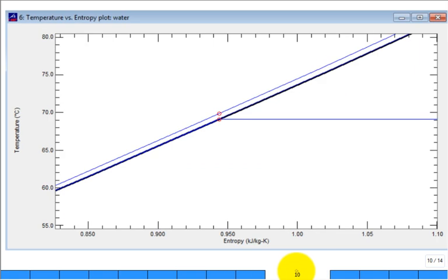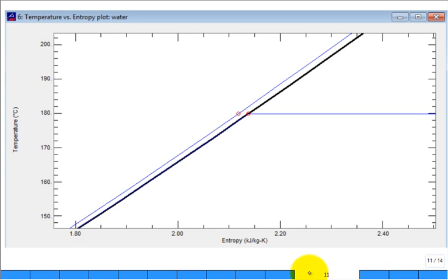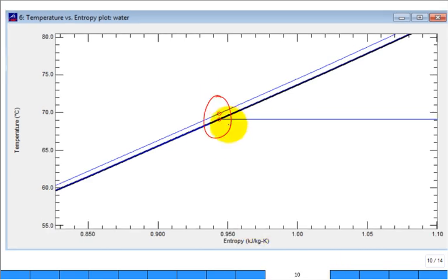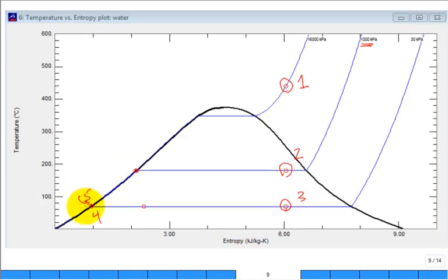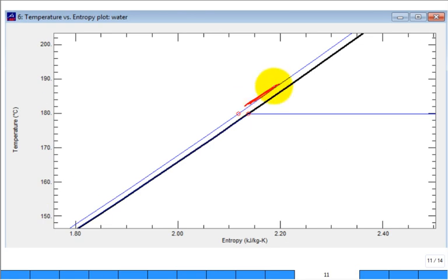Zoom in. No, this was the zoom in for the pump. So there's 4 and there's 5. Back on this one, there's 5 right there. Now, we had saturated liquid at the 16 megapascal. That's state 6. It's right on top of state 7. That was the second zoom in. This is at that high pressure, 16 megapascal. This is the saturated liquid going out at the bottom of the closed feed water heater.